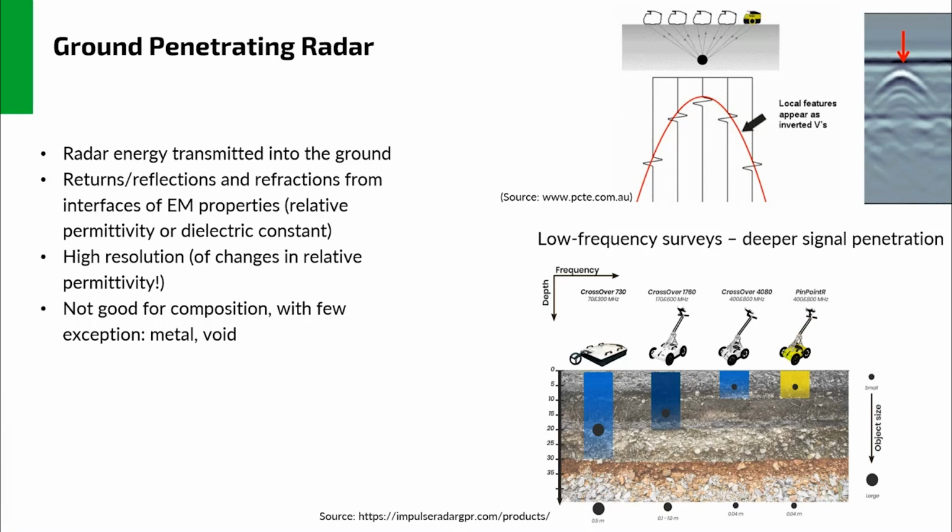If you are looking for something underground and you are not sure whether it's even possible to detect with GPR, it's best to contact us because we can give you an idea. It depends on the soil conditions, on the GPR frequency used, and obviously also on what kind of data collection method the practitioner is choosing.